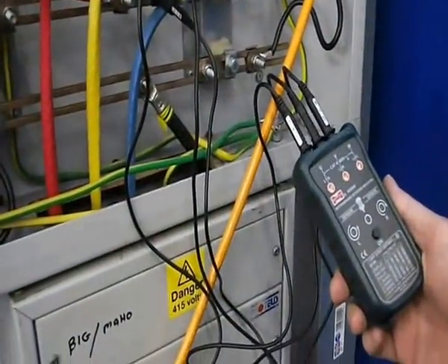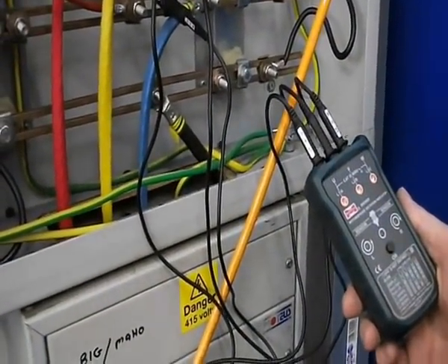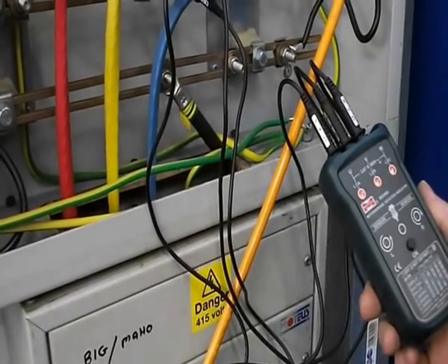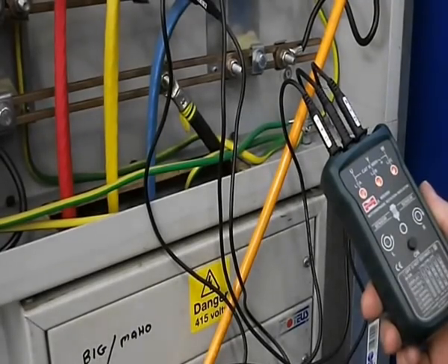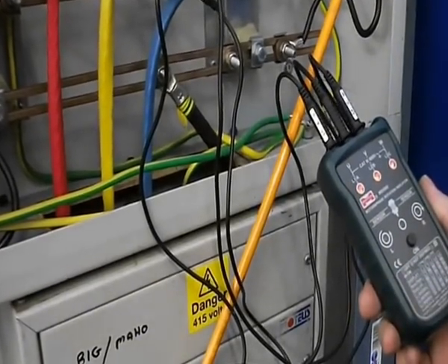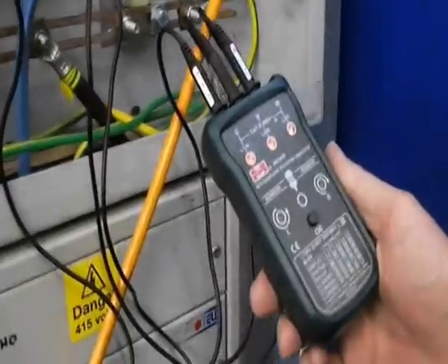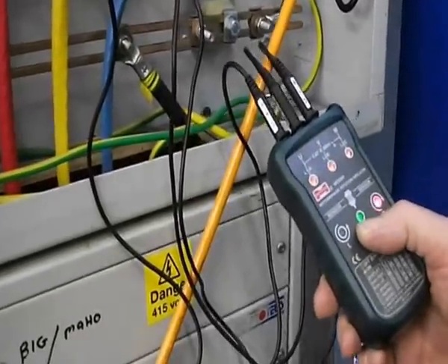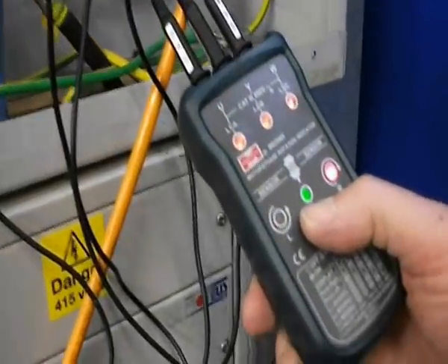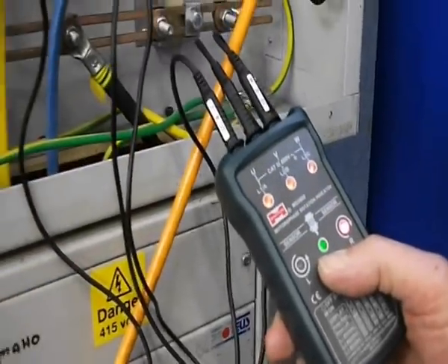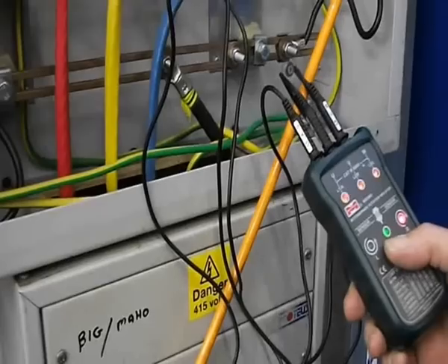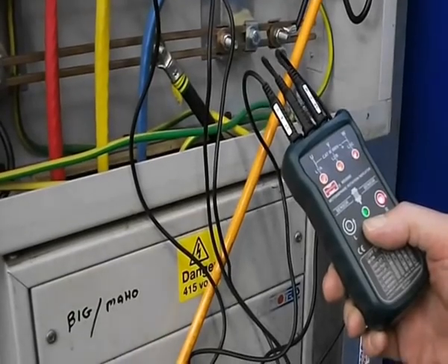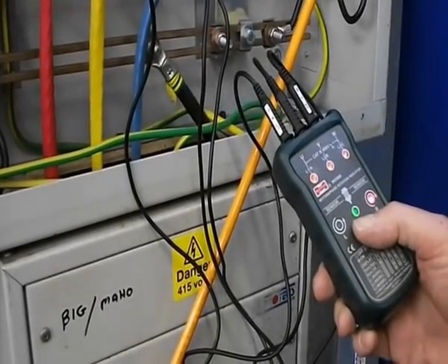The test about to be conducted here is a test of phase rotation. The phases should peak one after the other, spaced out 120 degrees or 1/3 of a cycle. The sequence is L1, L2, L3, and just here we have a phase sequence tester, and when the button in the middle is pressed, the lamp on the right lights up, hopefully it can be seen, and this indicates that phase rotation is correct. If phase rotation is incorrect, it will cause electric motors, three-phase electric motors of the induction type, to run in the reverse direction.